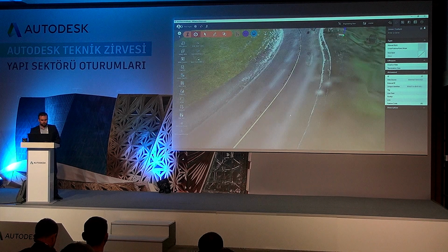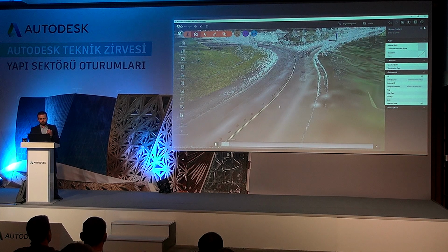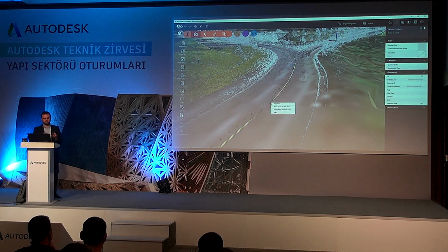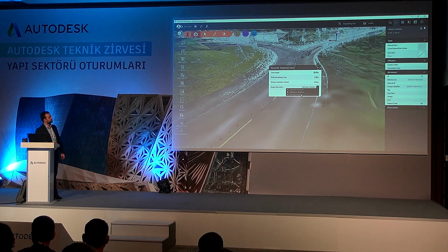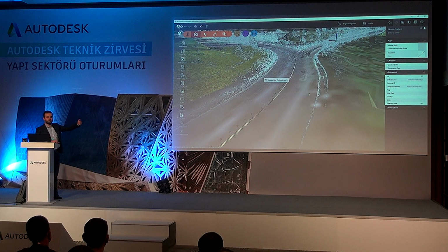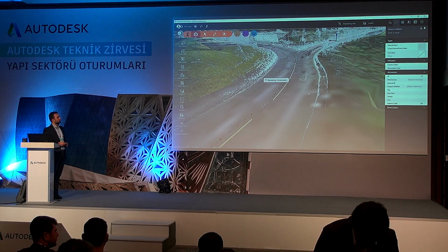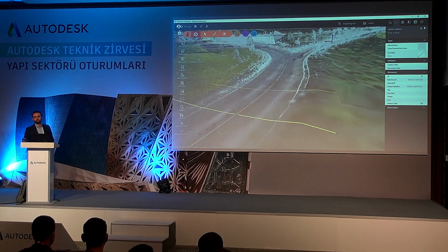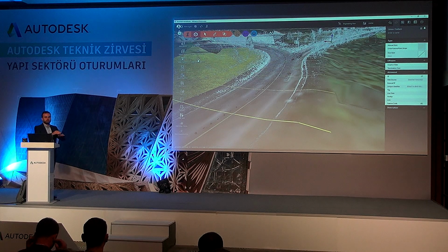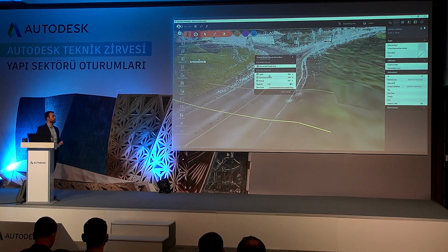Another thing, so we generated the surface, we created the feature lines automatically, we're able to check the cross sections, we can generate transverse lines, meaning I want to create like cross sections or lines across the length of the road. And I can specify at what distance, taking into the cross section in mind, and to what file format I want to export it. Because I would like to take all this data and send it to Civil 3D, from which I will create the existing surface of the road, and on which I will start my new corridor model.